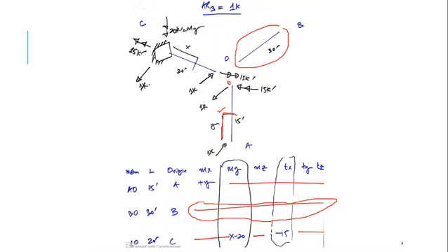This one kip in Z direction and this section is in Y. There should be a moment in MX. It is forming an anti-clockwise moment. It should be balanced with clockwise, and the magnitude would be 1 into Y gives us 1Y.